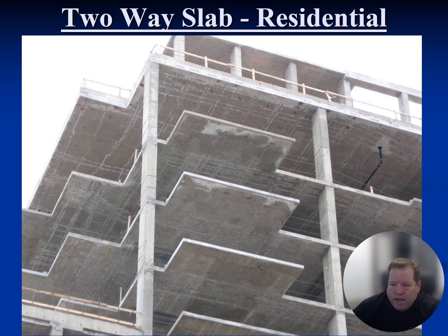You design accordingly. But the other thing about this photograph to look at is you can see, again, a relatively tall structure. Let's say this is 10 stories, relatively thin columns, relatively thin slab, and we're using stud rails for the punching shear strength. So again, you're having no cap, no beams. That keeps the floor heights down, shoring costs, reform, stuff like that, but this can make the building shorter than it would be in different materials. If you're in a high seismic zone, that decreases the overturning moment and the vertical distribution. So again, we are the shortest, thinnest structure out there.